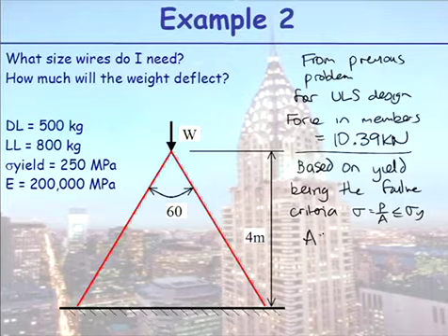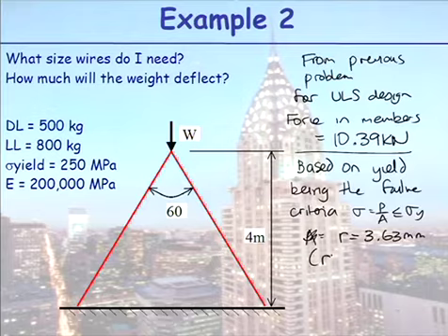Our area, we got an R value. We've done this calculation already. We chose an R value of 4 millimetres. Because that yield check we did in tension is the same as it is in your compression. So based on this thing not buckling but yielding, we need to have a 4 millimetre diameter rod in there. Is that okay with everyone? Radius. So this is the radius.